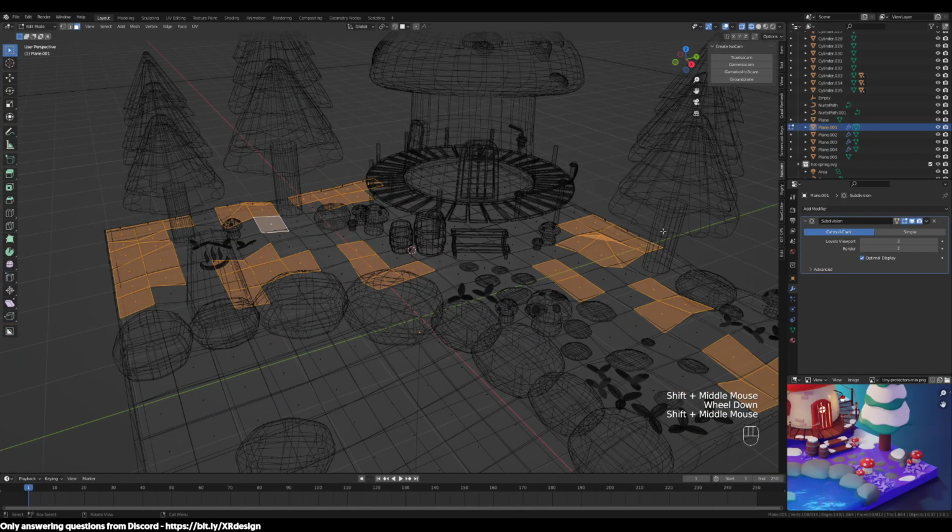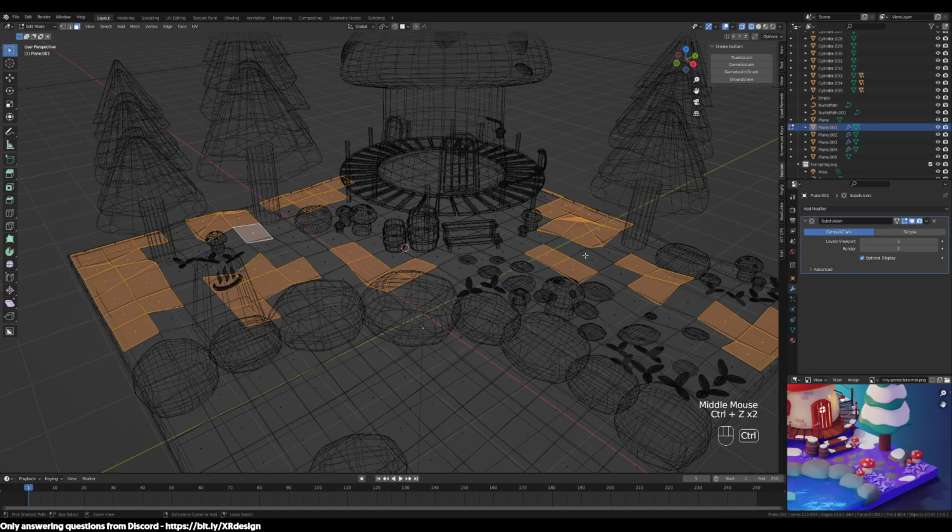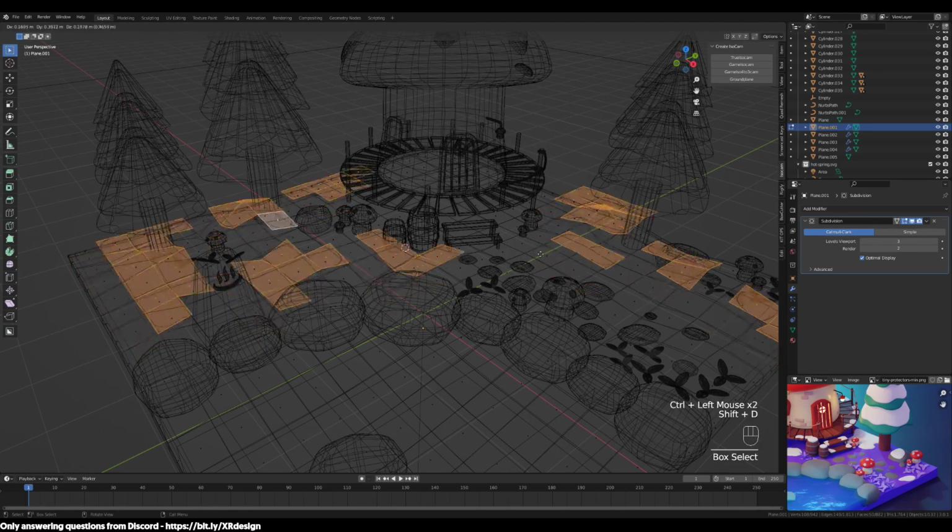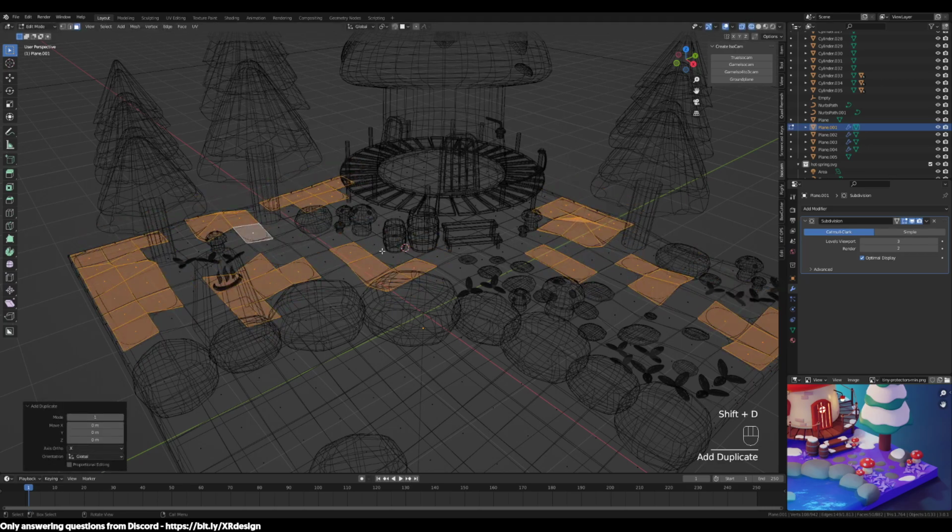Okay, by now, hopefully you're done. We're gonna do Shift D, just duplicate those tiles. Press Enter, don't move them. Actually, if you did want to confirm that selection exactly where it is, you might want to do right mouse click or escape.